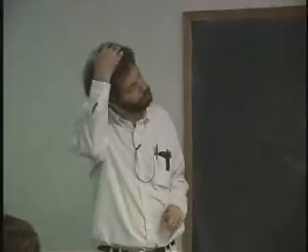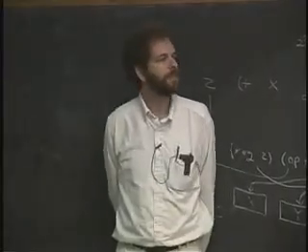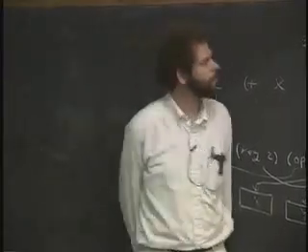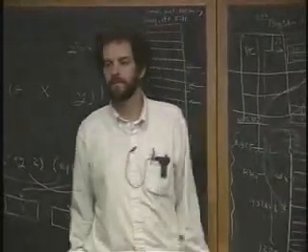And so rather than deal with that whole mess, we're just forcing everything to be on a 32-bit wide boundary. Theoretically, because we're only using words, we could actually have a 16 gigabyte main memory. Yes, so this is 4 gigawords long, which is 16 gigabytes. So if I said gigabytes when I meant gigawords, that's wrong.